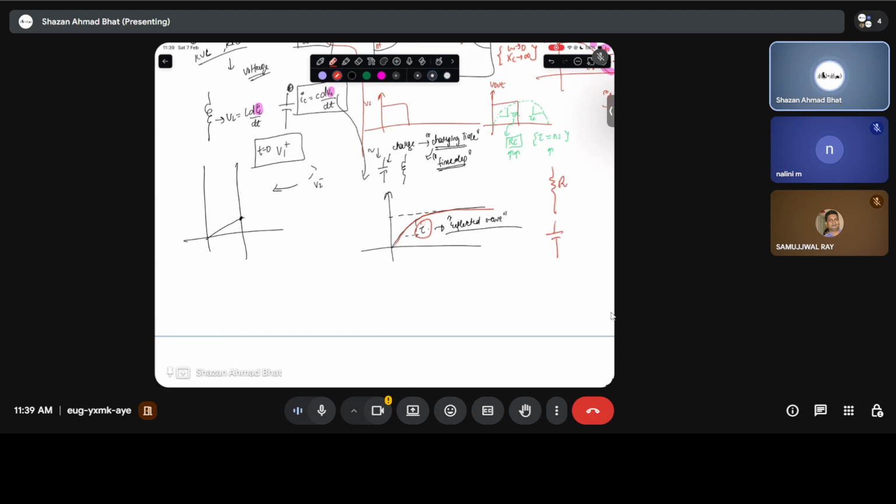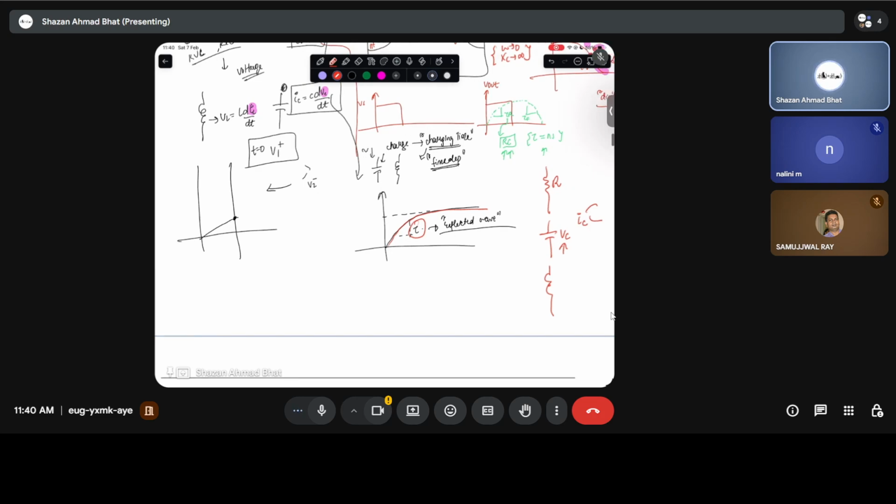But if there is a capacitive load or an inductive load, the voltage across the capacitor is a time dependent thing, because the current across it is time dependent. It charges and discharges depending upon certain time constants. So that's going to get reflected in the reflected wave going back to the source. So the entire thing now becomes time dependent.